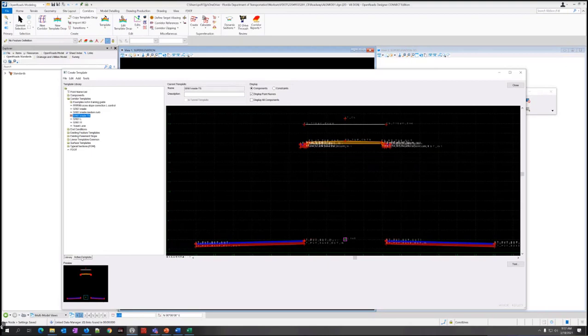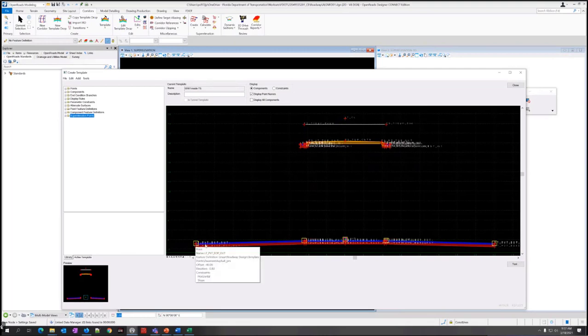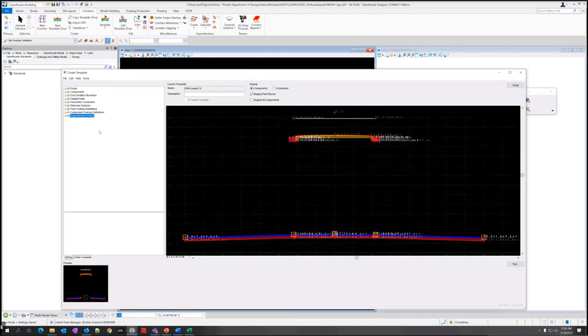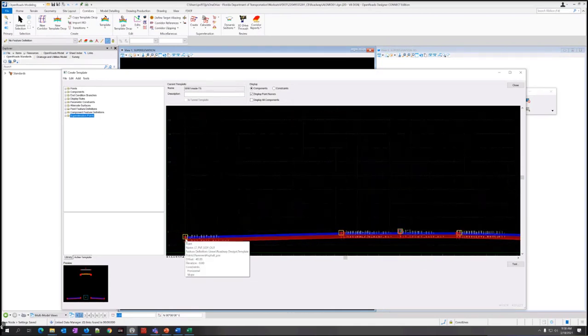And then switch over here in this tab to active template. This is step 4 that we're on right now. So we're looking for super elevation. What you want to do is click on the super elevation points right here. Just click on the folder, which will only show up once you click the active template. And notice that it highlights across here several different points. These are points that have super elevation flags turned on.